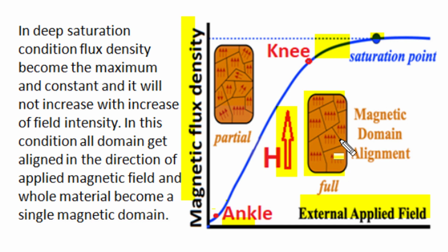magnetic induction in the ferromagnetic material. In deep saturation, the whole material becomes a single magnetic domain, so further increase in magnetic field saturates, and the dynamic permeability becomes only the permeability of air, as no more induced magnetic induction is possible after the saturation point.